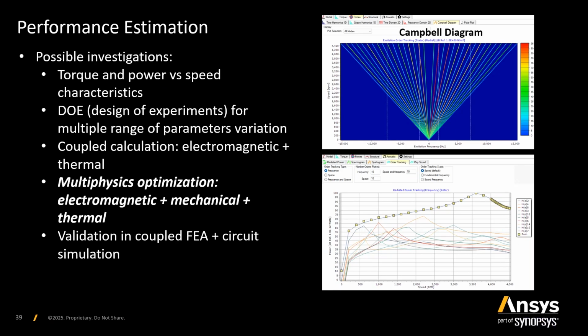This image shows that theoretically we would expect a high-frequency resonance, close to 100 decibels, somewhere just below 4,000 revs per minute. However, this machine will typically operate up to 3,000 to 3,500, which is mostly the spectrum where it will operate.